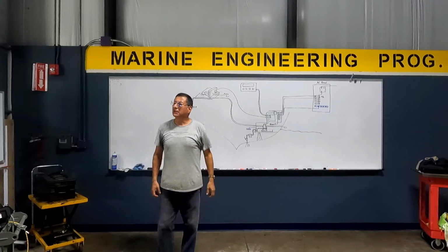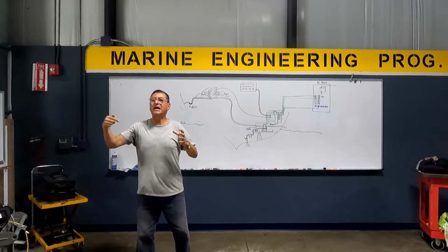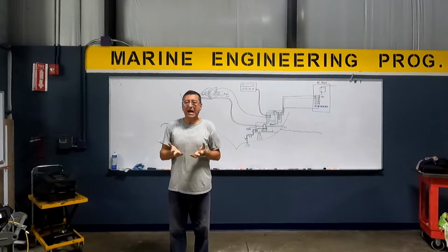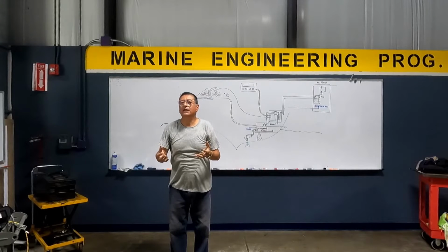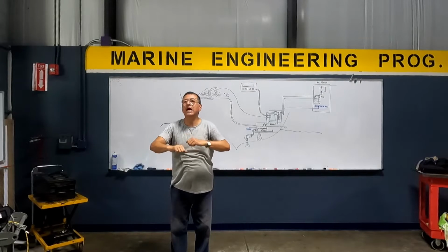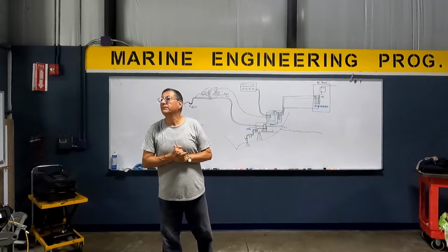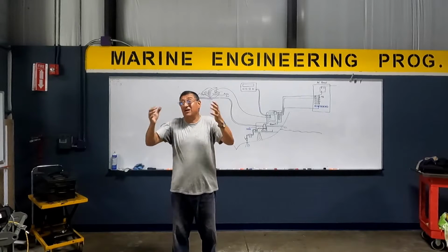Then you won't get any air. And then you see a big ice. You don't have enough amount of air passing through the frozen pipes. And what happens? Freeze up. Ice block, and suddenly the unit shuts down. And you see a lot of water come out. Correct. Or no water because it's a block of ice.